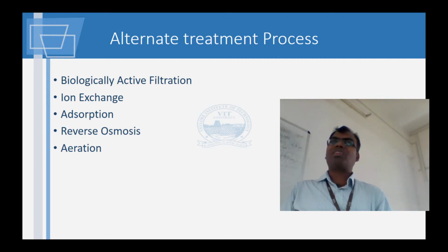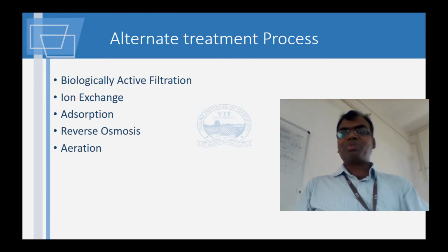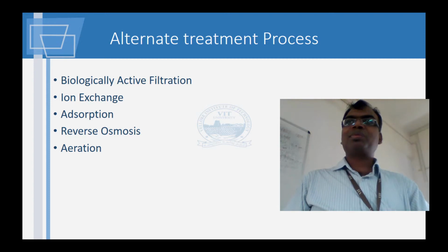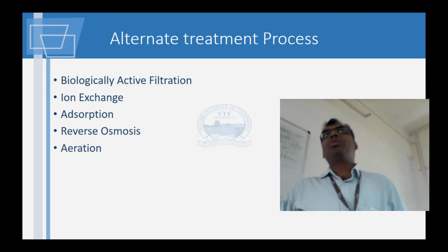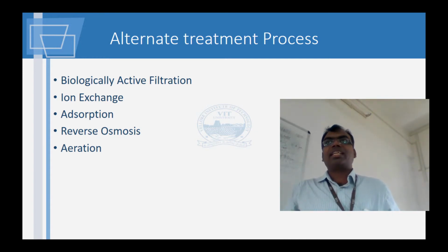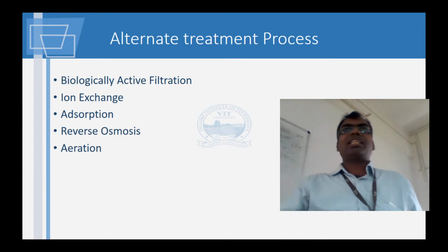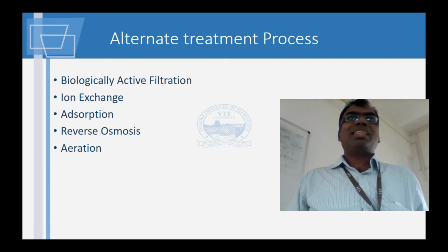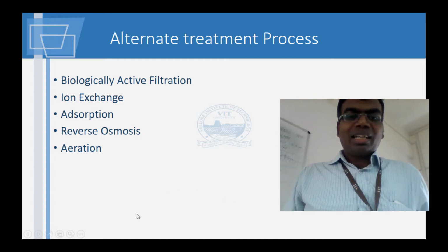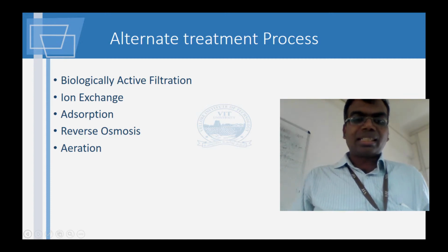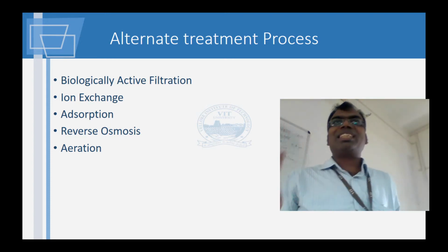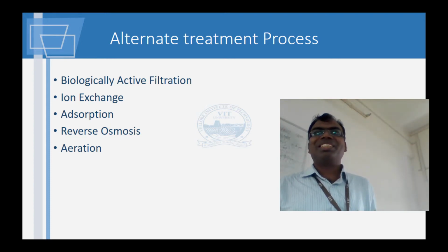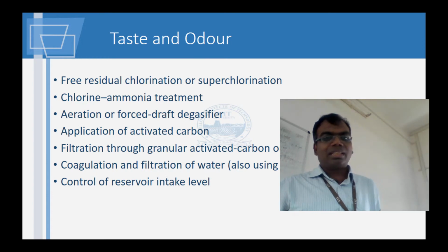And again, ozonization is also one way of aeration only. Okay, so for large cases, that type of aeration will be a problem. That would be more economical in the sense you may have such a huge aeration area and all that. Now everything gets reduced. And aeration actually improves the taste. Please remember that boiled water doesn't taste very good. So then taste and odor.